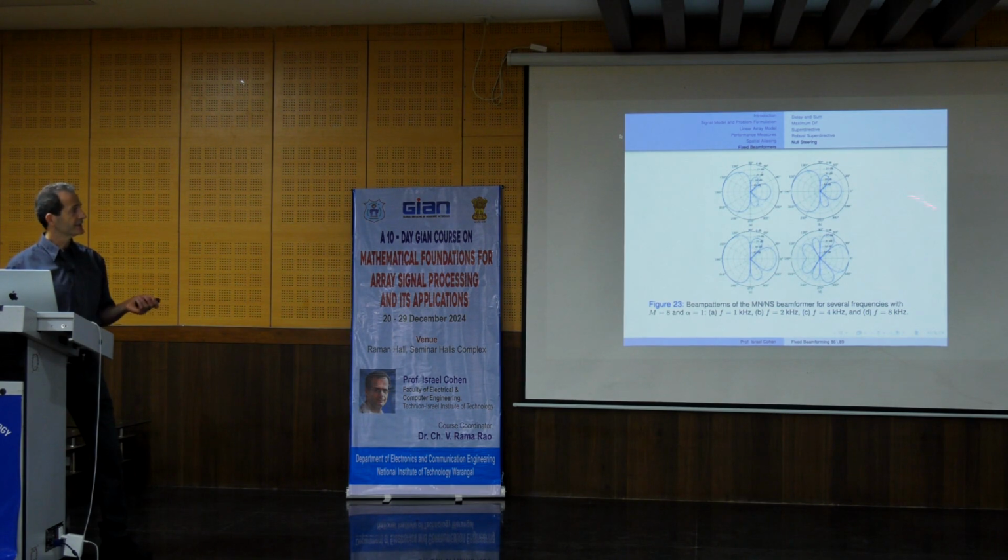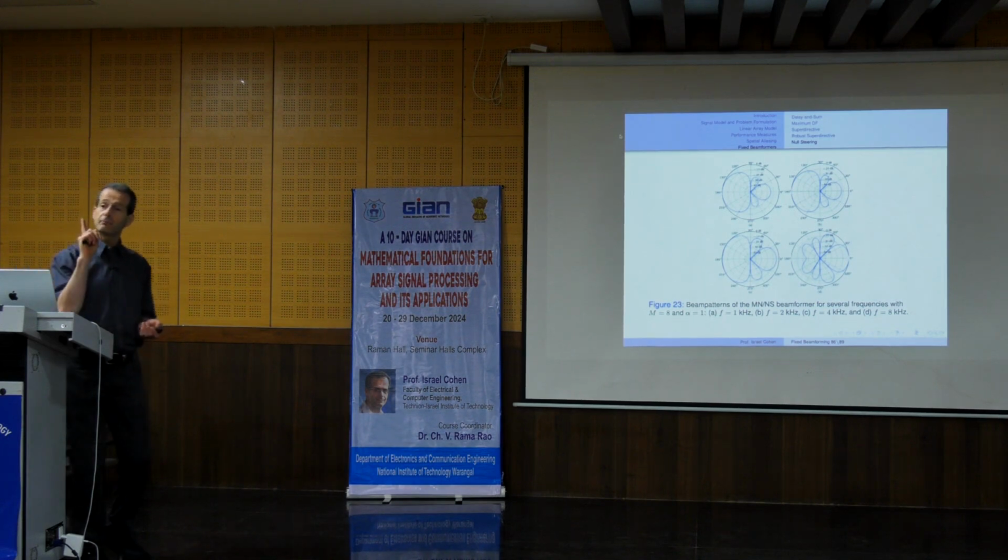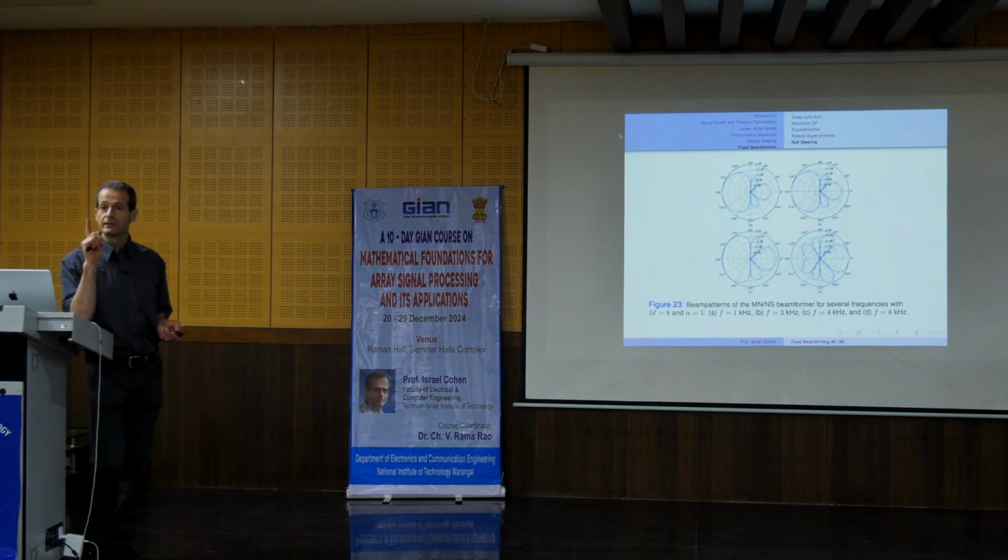But still, the integral over all directions is still larger than 1. So if you take the ratio between the gain in the desired direction and the integral, it's still larger than 1, which means that it doesn't amplify the diffuse noise if the noise comes from all other directions.